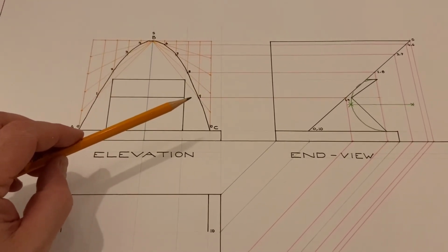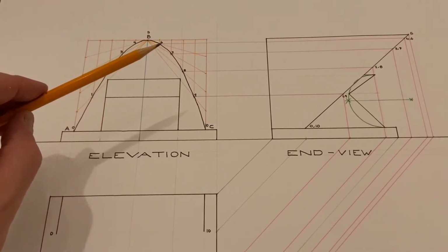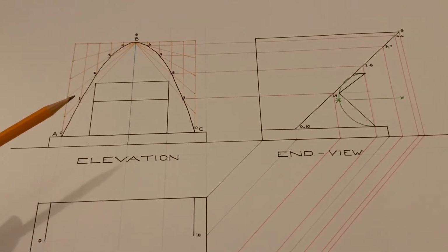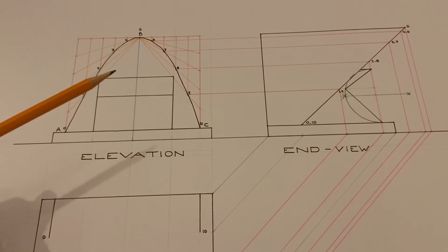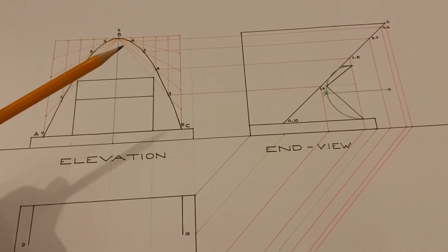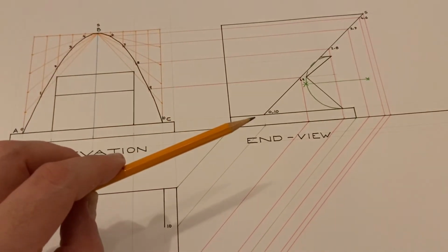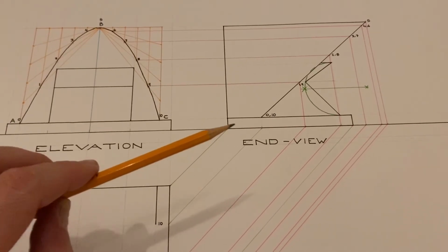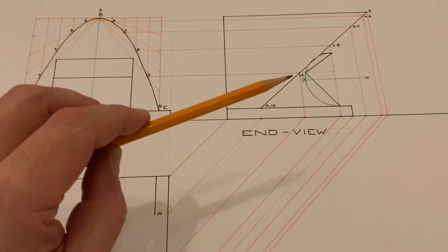So where you have these lines in elevation at 9, 8, 7 and 6, these would also line up exactly with 4, 3, 2 and 1. So there's no need to bring those lines across. It's only unnecessary construction running across the elevation. So we bring those lines across onto this diagonal sloping line, because this is the curve we are trying to find in plan. So all of those projection lines come over here and they stop on this line.